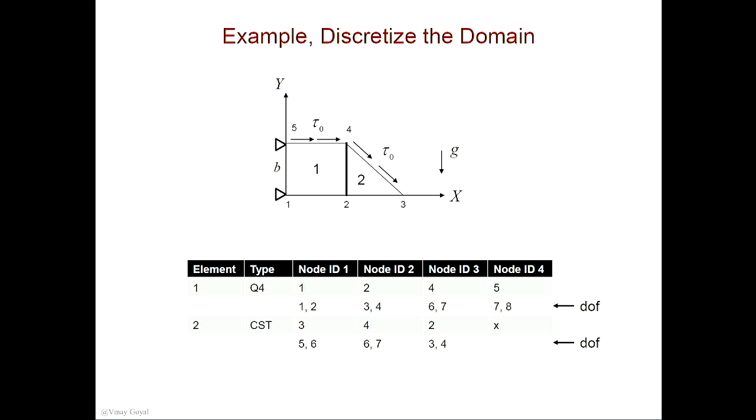Do we need to use isoparametric? If I was you, I'd use isoparametric because it will simplify all the calculations. You can just use one shape function for everything. The Jacobians will look different. Now you understand why I did two elements and not three. Less work, but I can teach you the concept.